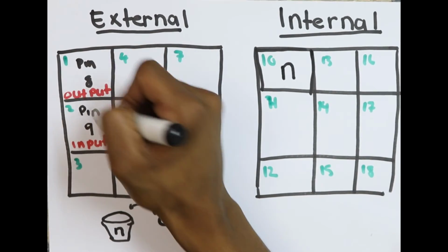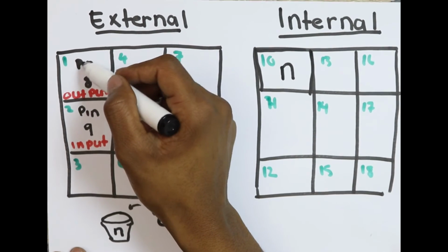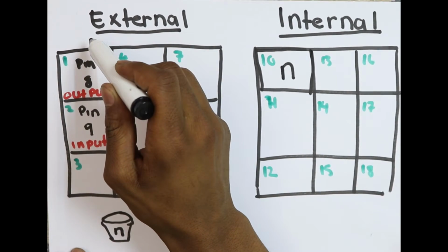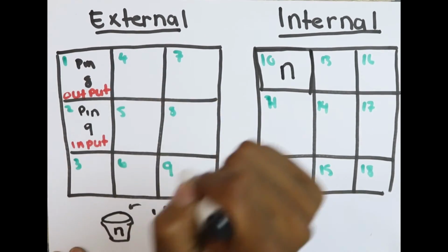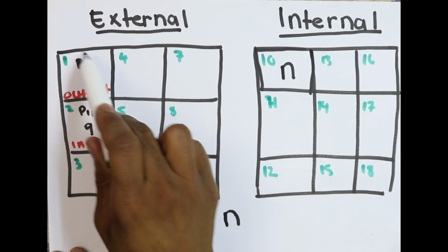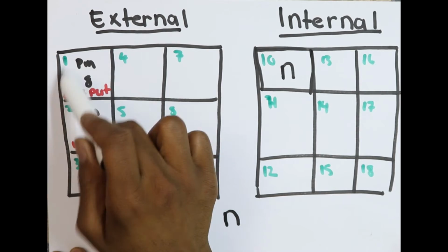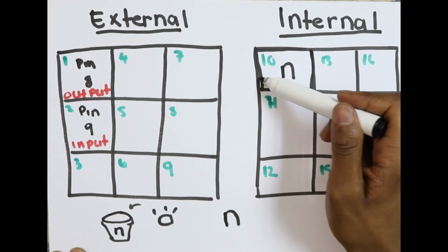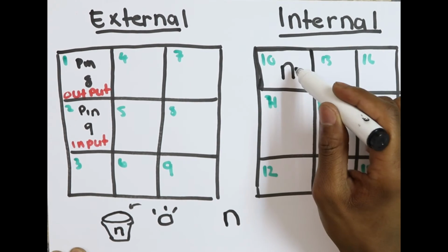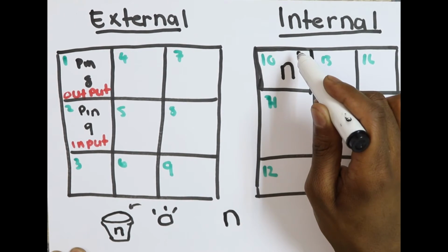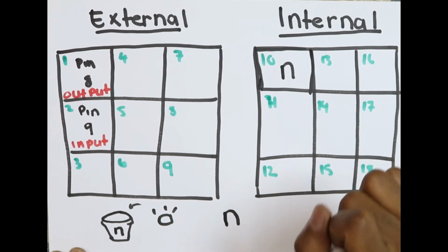So the same thing actually happened here. It's just that it already knew that I have a pin 8. But what this also says is that, okay, you have something called pin 8, go to memory, shelf number 1, reserve that space for information concerning pin number 8. Here, we're saying that in your memory, please keep a space for us where we are going to store values that count how many times the LED goes on and off.